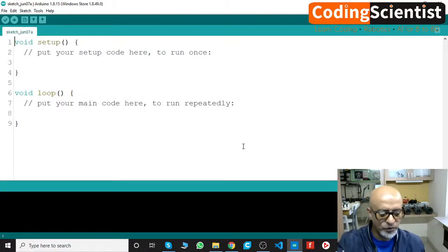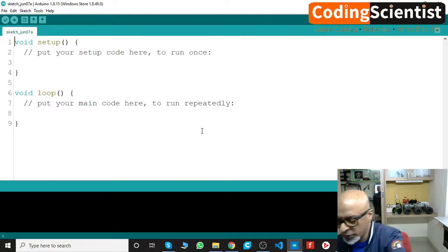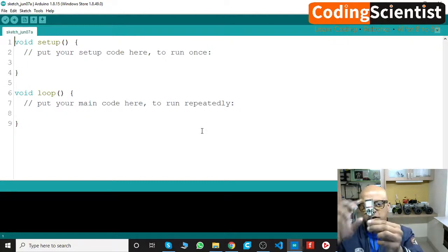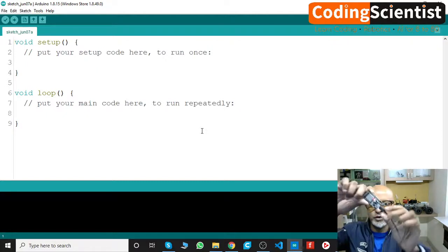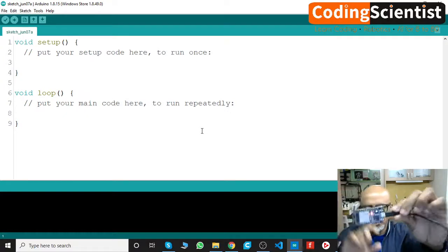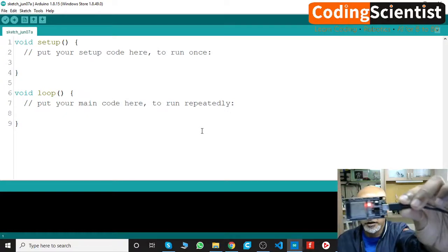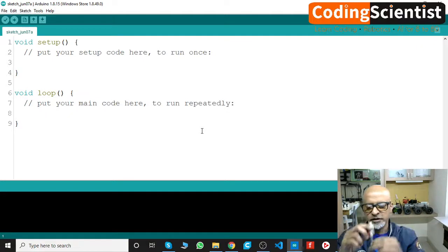Once you close it, now let's try to connect it. Let's do some basic testing, right? So I hope your board is connected. Once you connect your micro USB to your ESP32 board, like this, all right, you will get a red light. Leave it as it is.